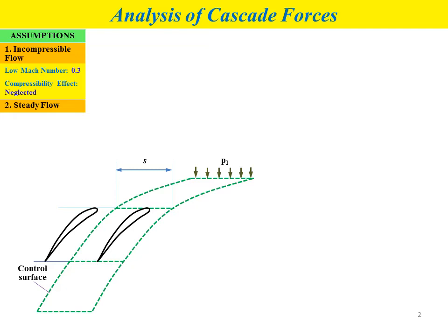We will have a pressure at the inlet of the cascade and also a pressure at the outlet of the cascade, and the directions of both pressures are different, because we will have a pressure difference throughout the cascade blade. P stands for pressure. We also have the inlet flow velocity vector represented by C1, and the outlet flow velocity vector represented by C2.